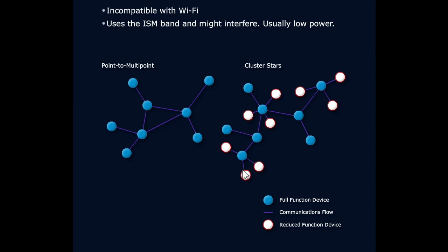Now, the way that a ZigBee network works is kind of similar to a Bluetooth Piconet, in that there will be a network coordinator, a particular device that is an active device. It's a full function device. Not only could it potentially measure things or perform actions, interoperate with the physical world, it's essentially what is responsible for the establishment of the ZigBee network itself, which can then also branch out to other devices, and so forth.